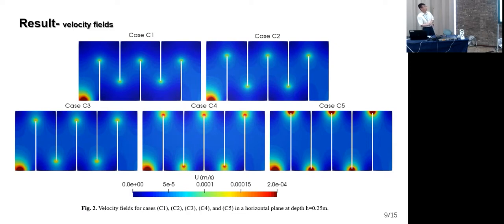It's simply because of the smaller cross-sectional area caused by the longer baffle. And the velocity for the dark blue area is 0 or extremely low, representing the dead space in the reactor. We can see that most of the dead space is concentrated at the corners in the reactors.